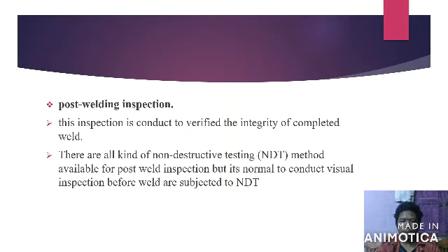This inspection is conducted to verify the integrity of the complete weld. There are all kinds of non-destructive testing and destructive testing methods available for post-welding inspection, but it is normal to conduct visual inspection before welds are subjected to NDT.